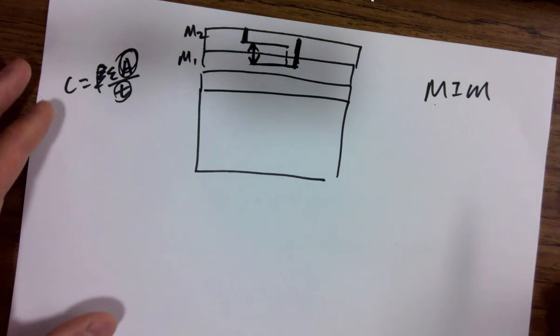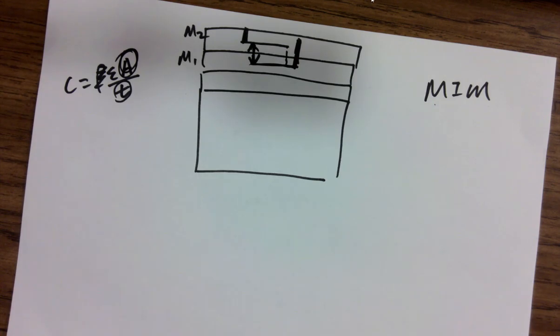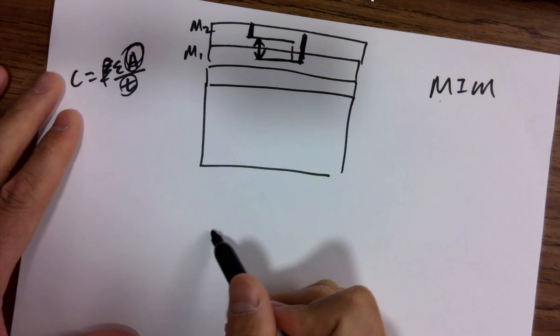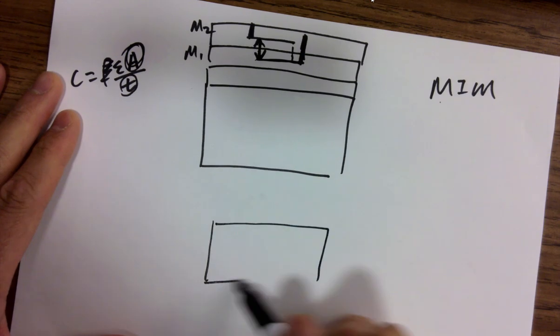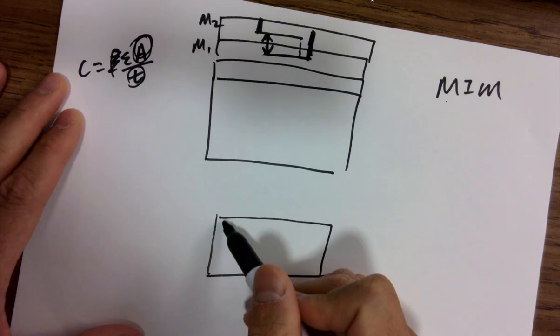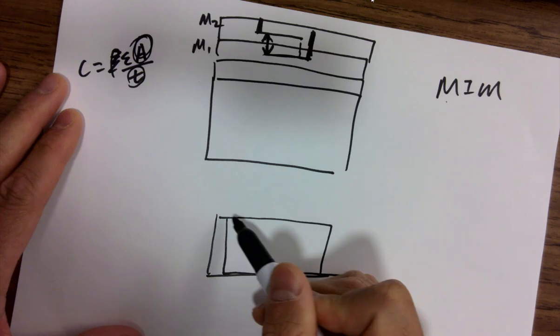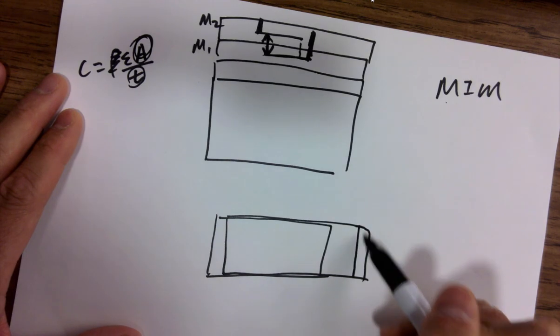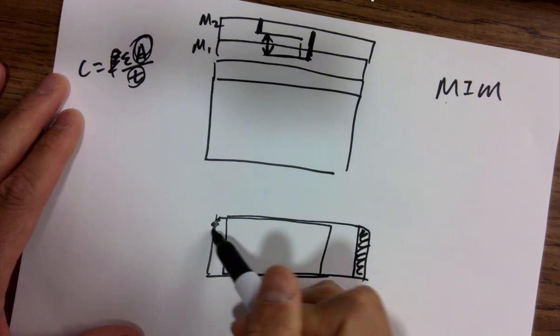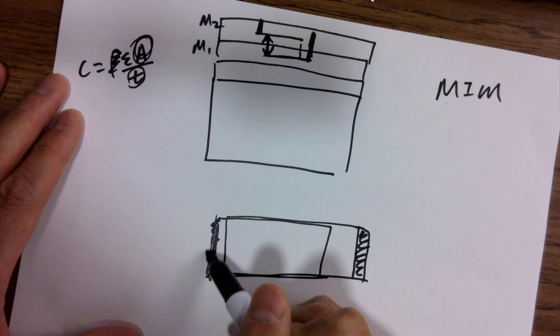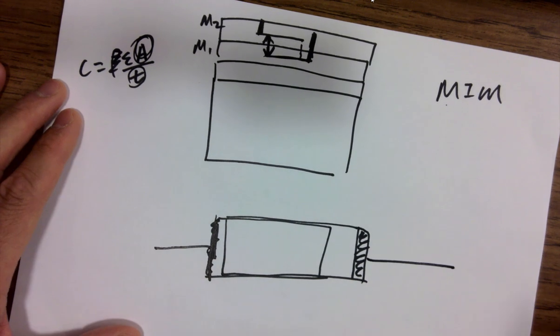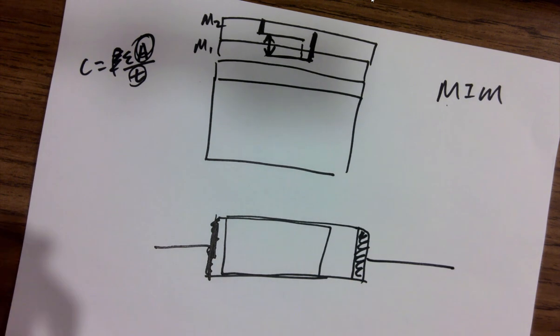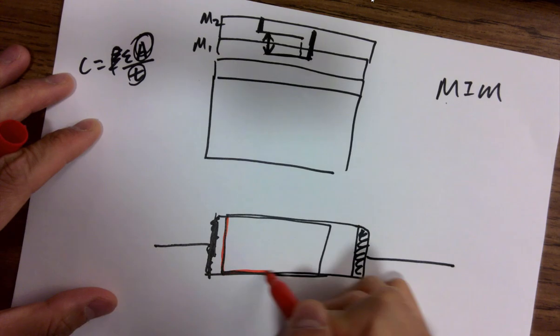When you are doing the layout, looking at the monitor screen with the Electric VLSI software, you are able to draw a capacitor by drawing a box of one layer, and drawing another box of another layer. I have a lot of vias over here, so you can make connections. The effective area is only this overlapped area for the cap.